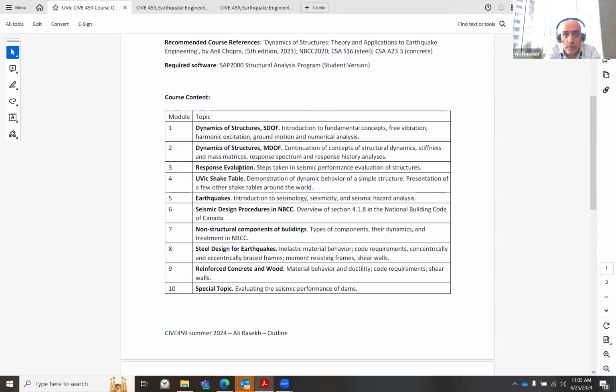Another very important topic for special structures or buildings is liquefaction, which they study a lot. We do less of it for regular buildings. As I said, try to avoid it, run away from it, or give it to your geotechnical engineer when the quality of soil is low and it's liquefiable.